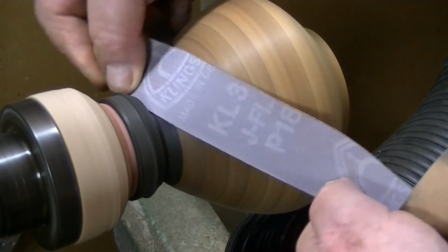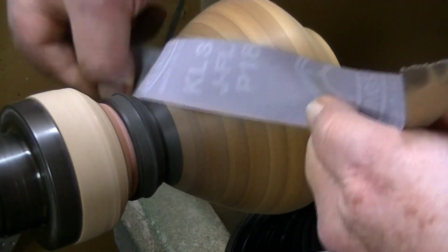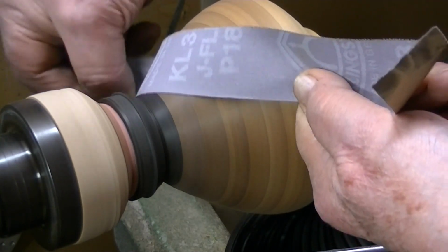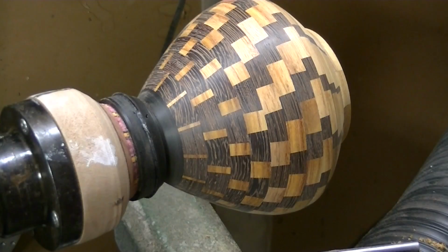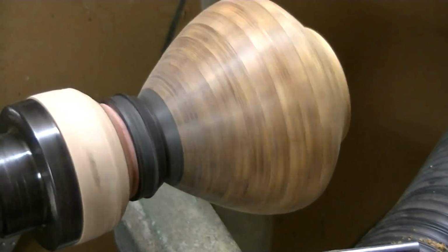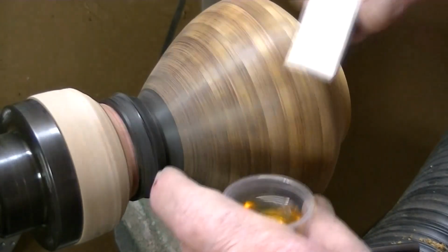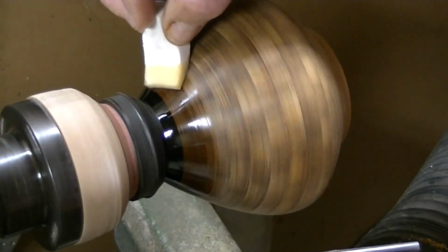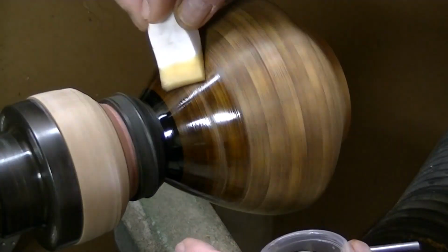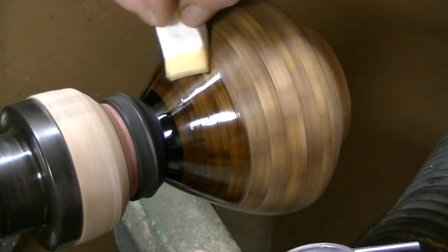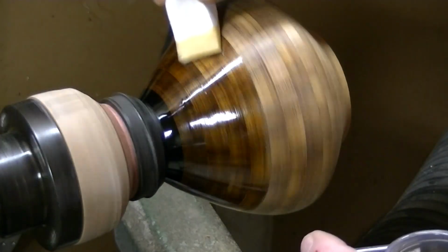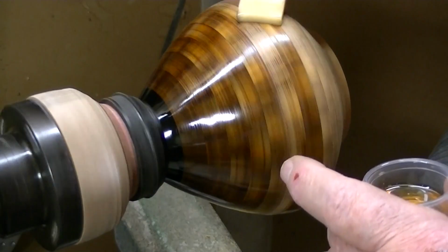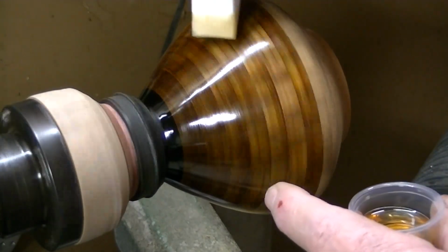Once that's been shaped properly, a little sanding here to finish up that area also. So we've got it done. Now it's time to see it really begin to pop. So I've turned the speed way down, and I'm going to apply a little of my Minwax wipe-on poly, the clear coat. And the first coat goes on fairly heavy because a lot of it will soak into the wood grain, acting as a sanding sealer, or a sealer in general.